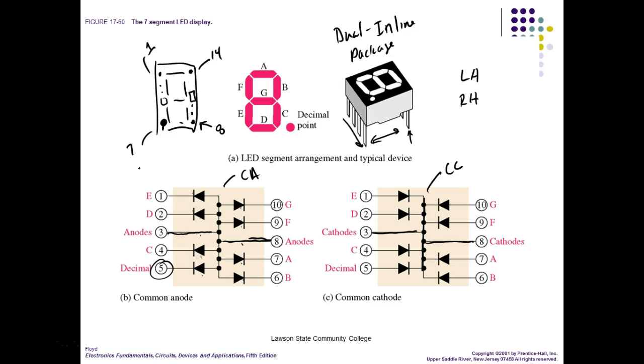So how would we check an LED if our meter will check them? That's one thing you need to find out. I'm going to come over here, pull out my resistor, and put my negative toward the cathode. Oops, I need to put it on the diode scale.